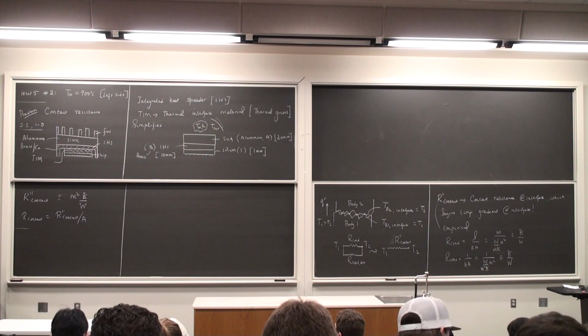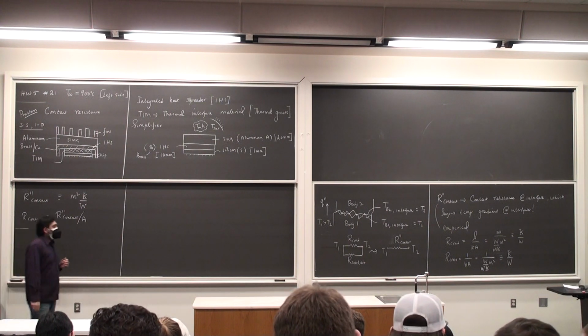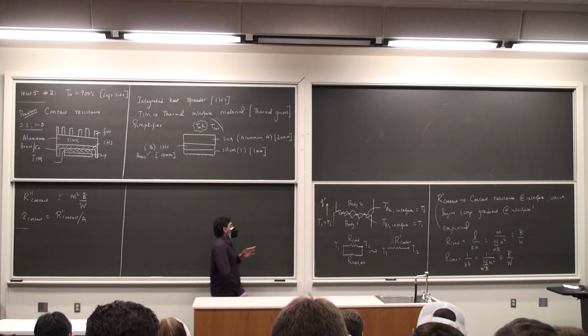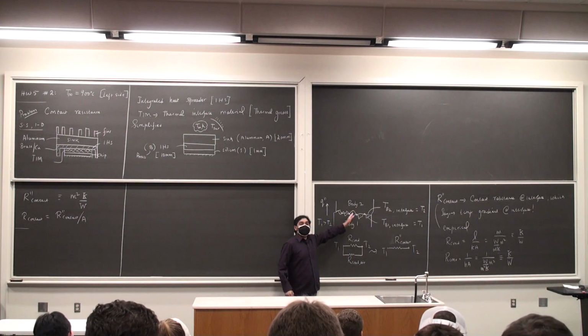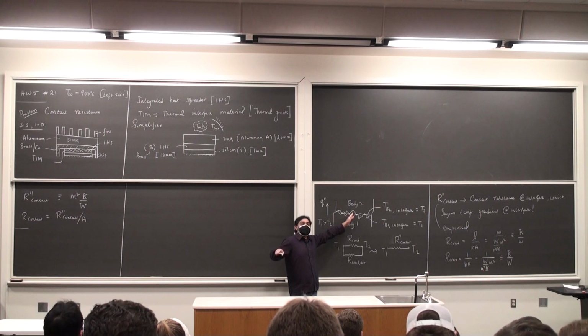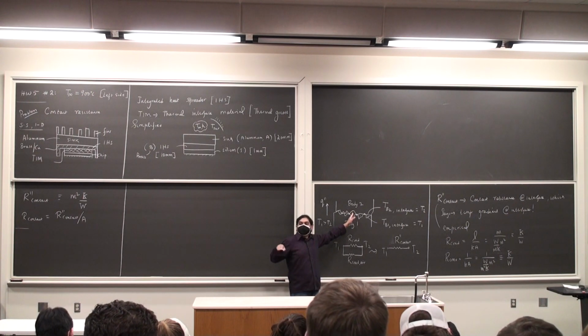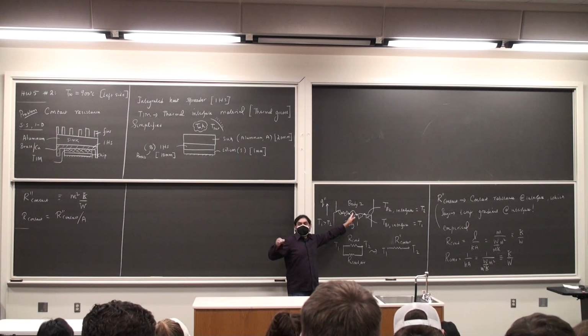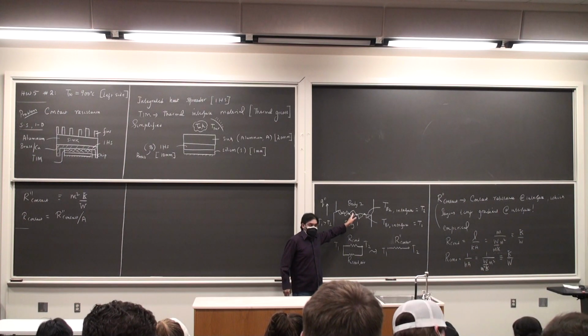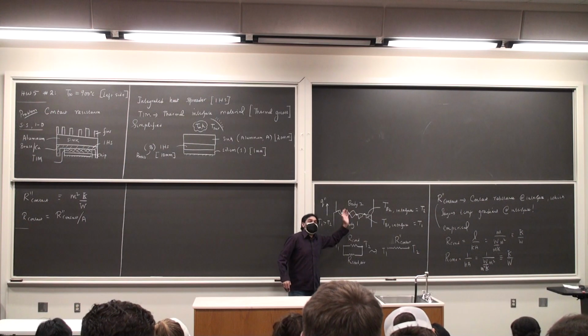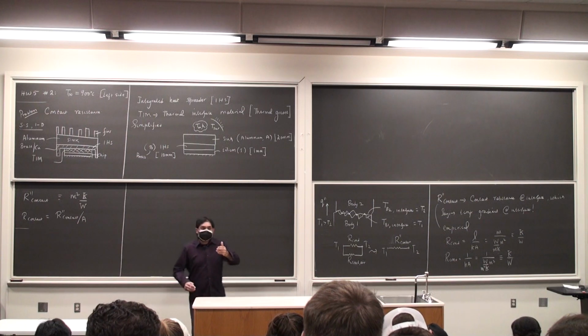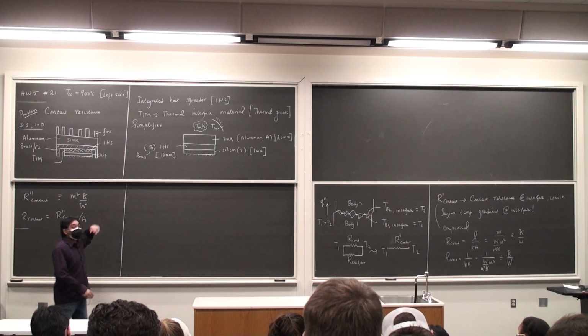And what people typically do is, okay, you obviously see that I have asperity contact, but then there is air here. So rather than have air there, I will rub some thermal paste or thermal grease on it, whose thermal conductivity is obviously better than that of air, so that I enhance the heat transfer going through. And that is the exact reason why we have this thermal interface material.